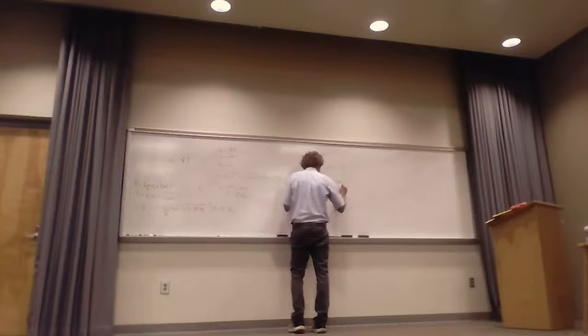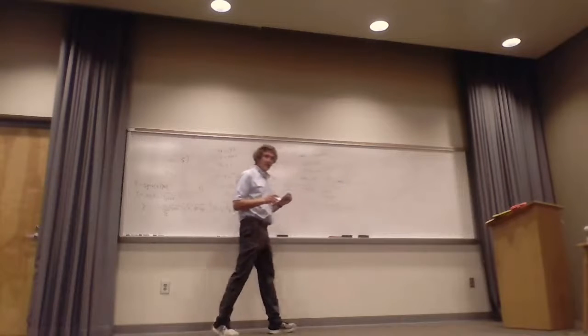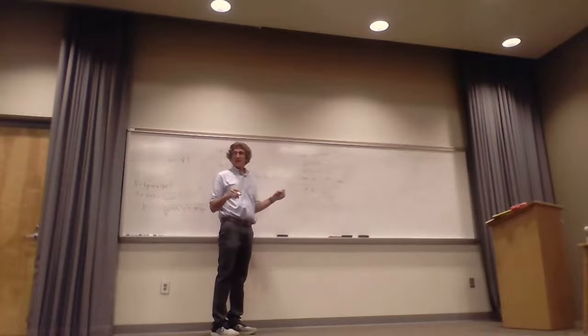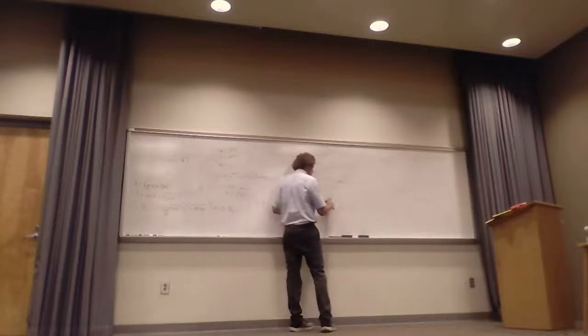Well, eta is the square root of j omega mu over sigma plus j omega epsilon, technically, right? Do we need the j omega epsilon for this problem, class? No, because we've already established the conductivity is much larger than j omega epsilon. So we can just get rid of that.